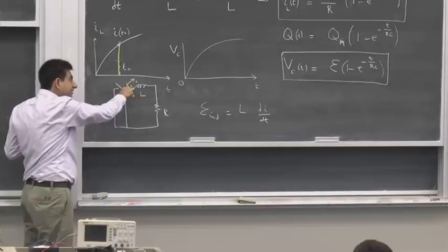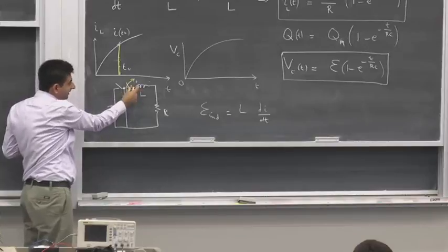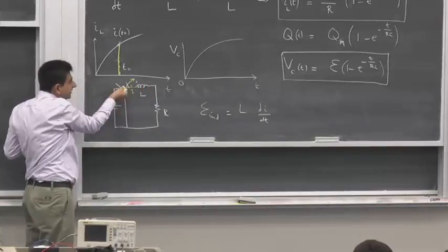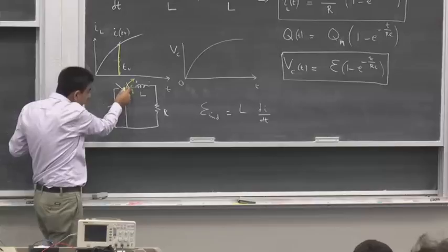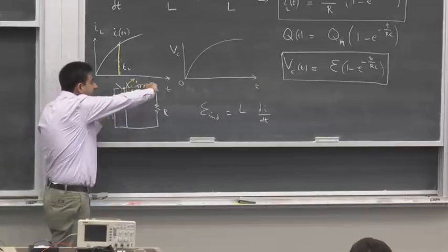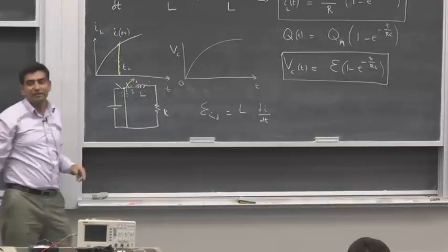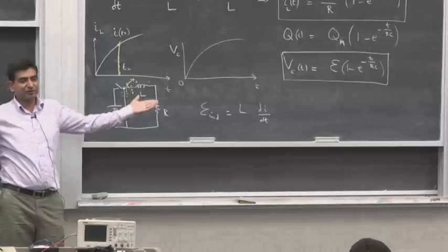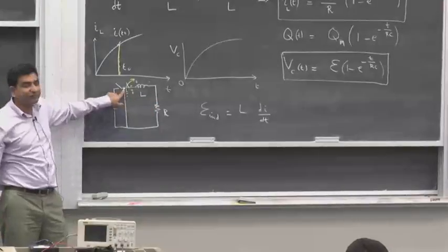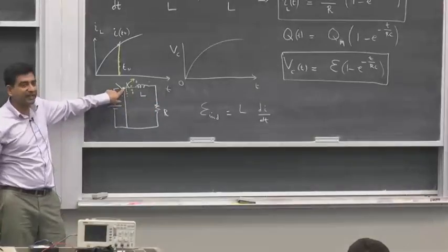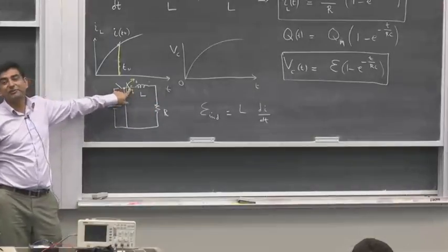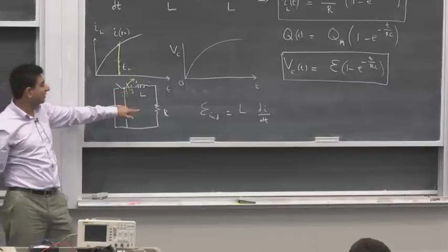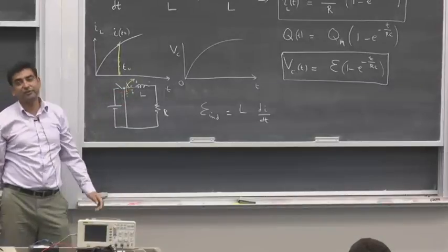So this is a conductor, so all of this positive charge is collected here and all of this negative charge is collected here, and the charge is evenly spread out in this conductor because the current is not flowing, the switch is open. So this terminal of the switch becomes negatively charged, this terminal becomes positively charged because you suddenly drop the current to zero.